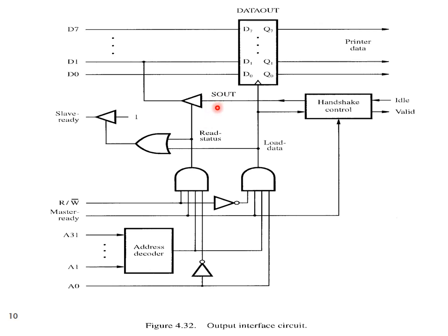which is now being set as 1, will be placed on the processor bus D1 line and it will be sent to the processor. Now the processor understands that the printer is ready for printing. So what will the processor do? The processor will send the data that is to be printed through the data lines of the processor to the output interface of the printer, that is they will be now available inside the data out register of the output interface of the printer.